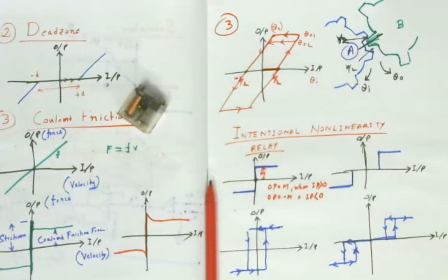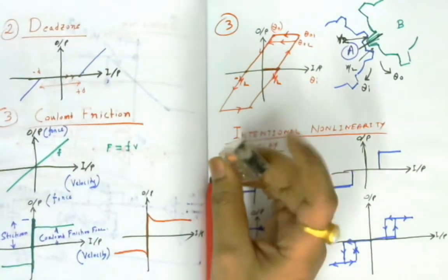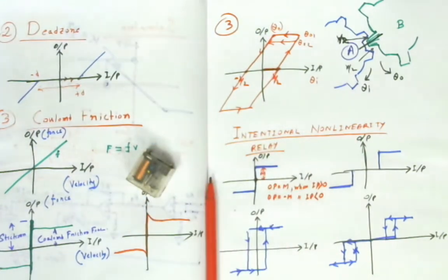Now suppose I have a 5 volt relay, and that means the relay coil requires 5 volt to be energized. Now suppose you have a variable DC supply, so you can raise the voltage gradually. Say I can apply 1 volt to the relay coil, 2 volt, 3 volt, and 5 volt. But any relay coil requires a specific amount of voltage and current. Suppose if you apply 2 volt to a 5 volt relay coil, you do not expect the relay coil to be energized.